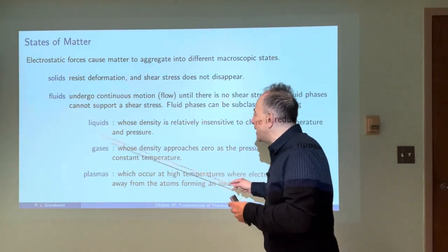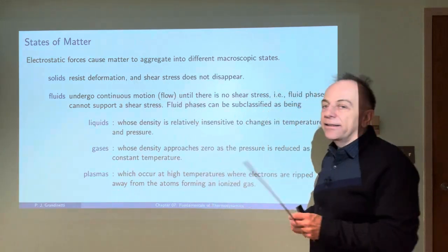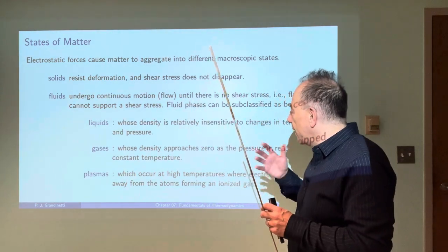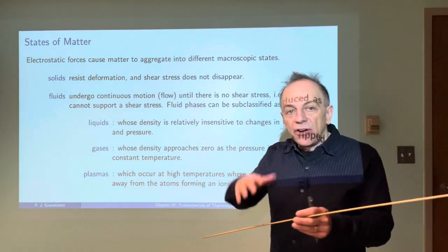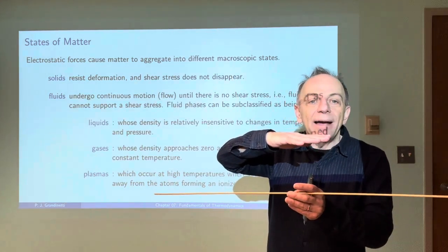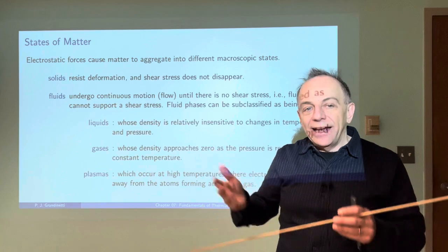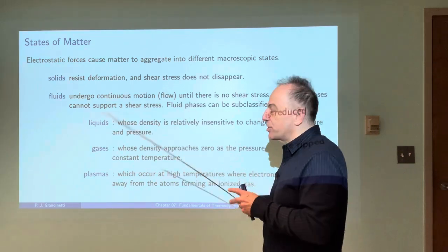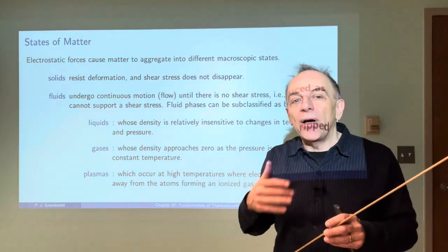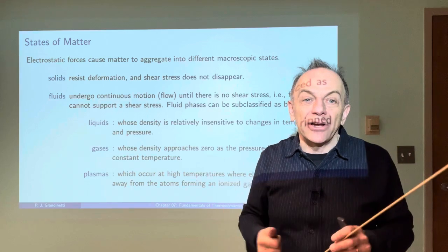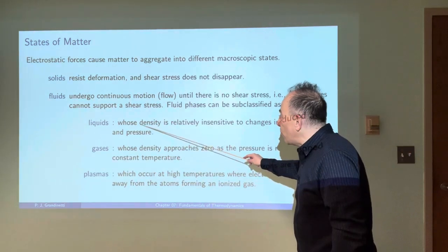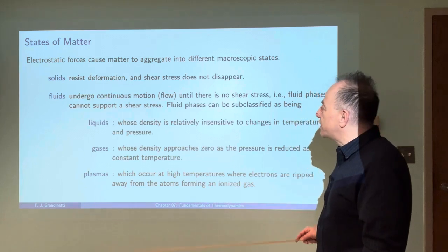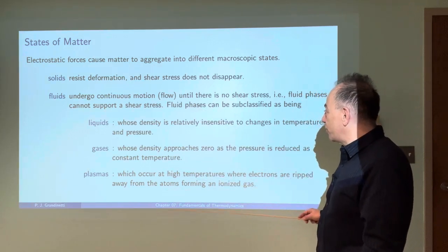And generally speaking, all of these are slightly subjective, because even solids, if you apply shear stress to them, over time they will start to deform and they will not support the shear stress fully. So it's somewhat relative here, but it depends on the time scale in which you're looking at these things. But liquids and gases are fluids that won't support a shear stress.